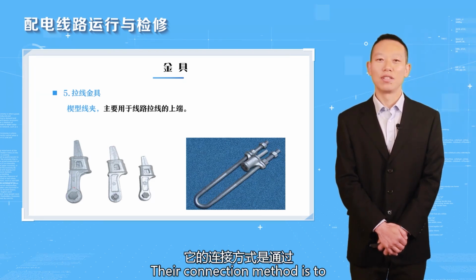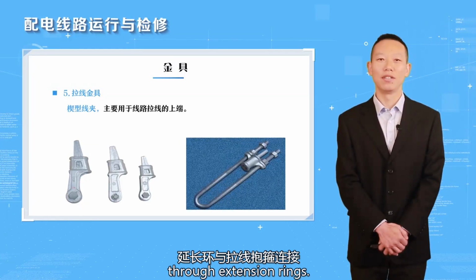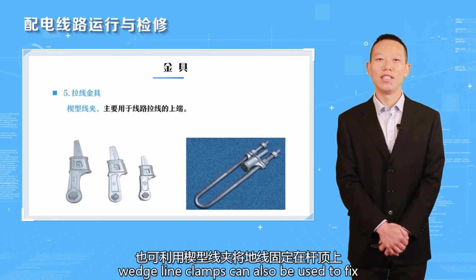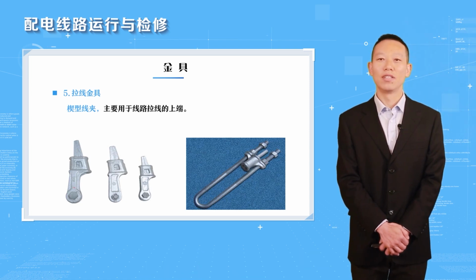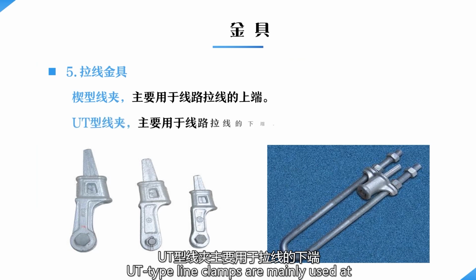Their connection method is to connect with tension line clamps through extension rings. In lines with ground wires and voltage levels of 35 kV and above, wedge line clamps can also be used to fix ground wires to the tops of towers and bear the tension of ground wires. UT-type line clamps are mainly used at the lower end of tension rods.